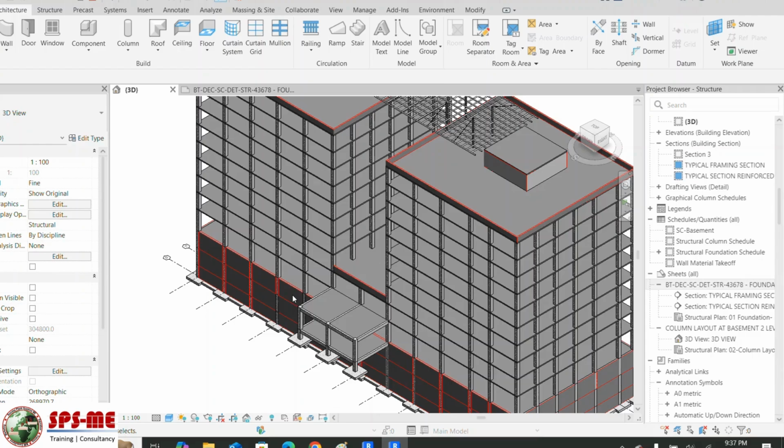If we wanted to take the quantity takeoff of the rebar, everything has to be created. But it depends on the scope defined for your project. So normally in structural, if it is LOD 350, meaning consultant drawing, only the minimum requirement. That means they are just creating one or two reinforcements over there, not for everything. Everything will be there for the as-built drawing and all those things.